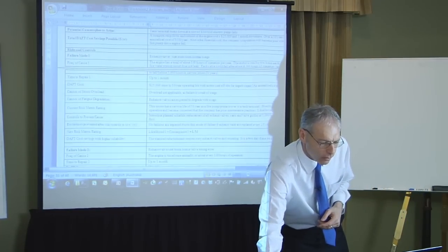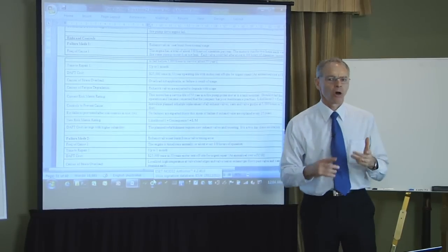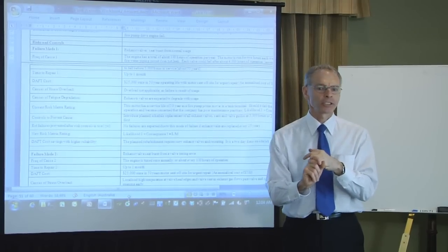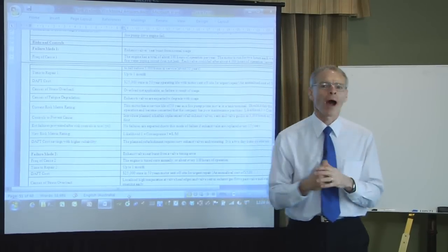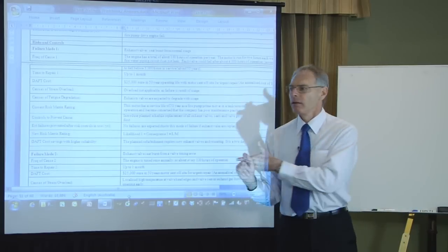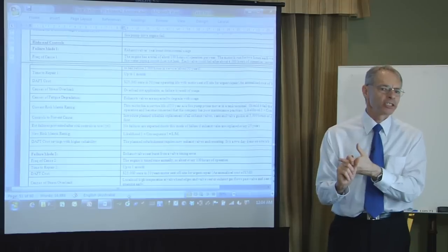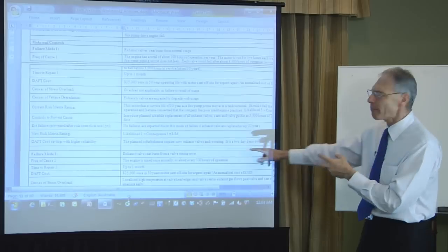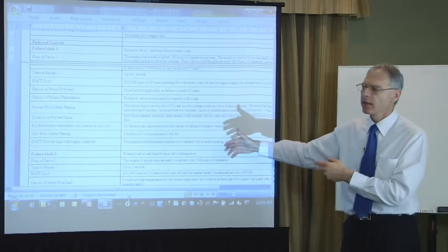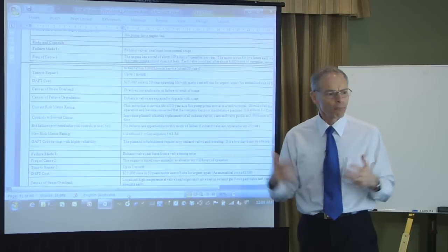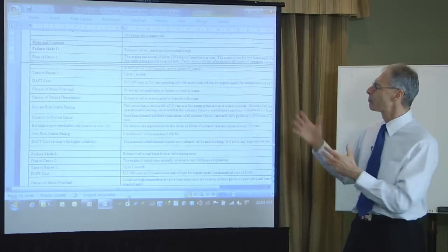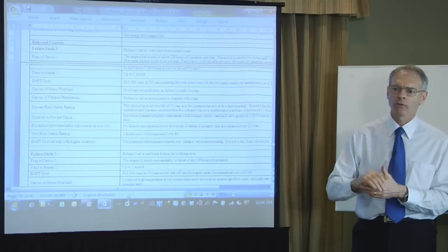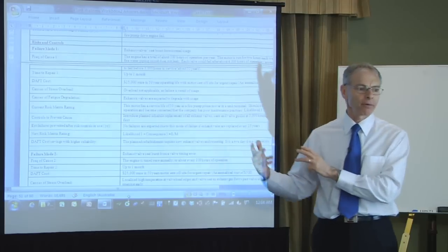In the end, what will happen with this particular machine, we're going to have very good procedures on how to maintain it well and how to operate it well, and possibly condition monitoring. We're going to introduce, if necessary, some sure ways to make sure that the mixture, the lean richness of our fuel, is correct. We're going to make sure that the timing is correct. Because if timing will burn the valve, if a lean mixture will burn the valve, they cannot be allowed to happen. So what will I do to prevent mistiming, to prevent wrong settings of the fuel-air ratio? Because they will happen.